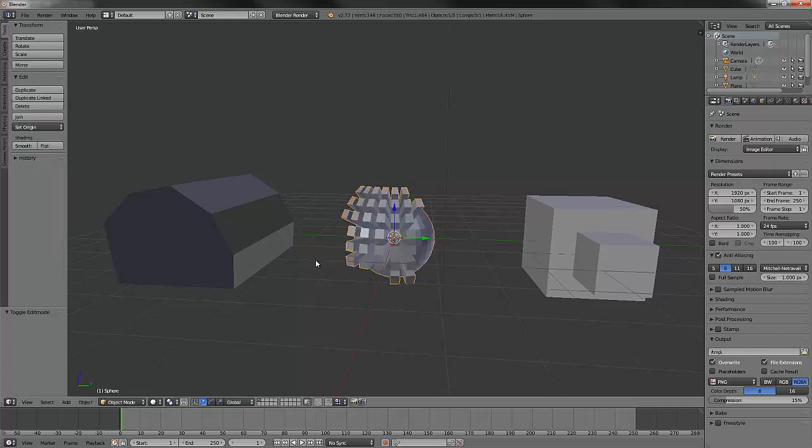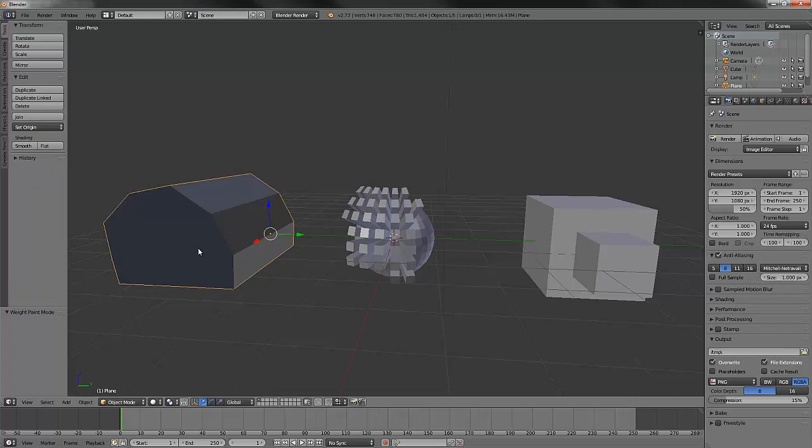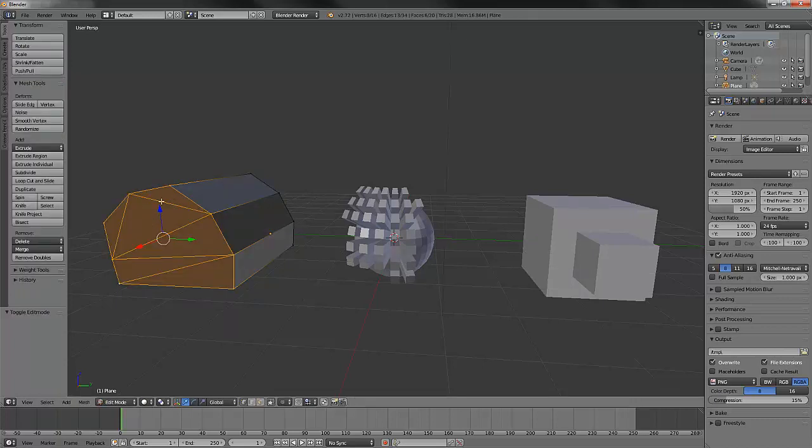We've learned that we can extrude not just faces, but also edges and vertices. We've locked our extrusions to an axis or to multiple axes by using our axis keys, or by using the shift key and the axis that we don't want, so that we can move in the other two simultaneously. We visited our F key and Alt F to either fill in our extrusions with an n-gon face, which means more than 4 vertices, or with triangulated face.